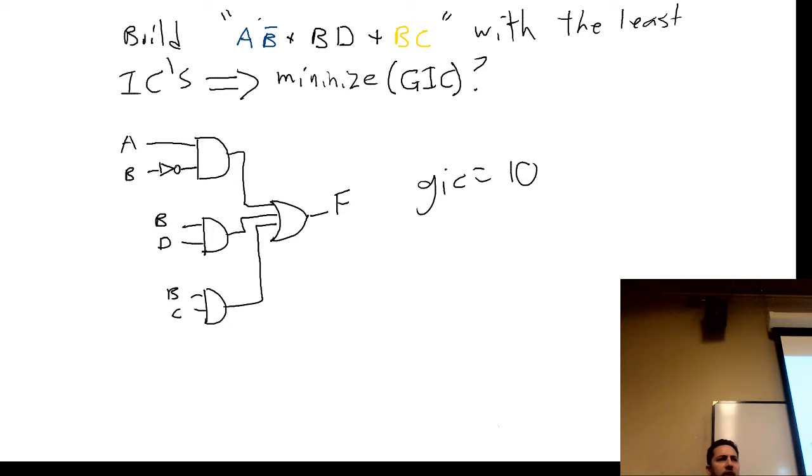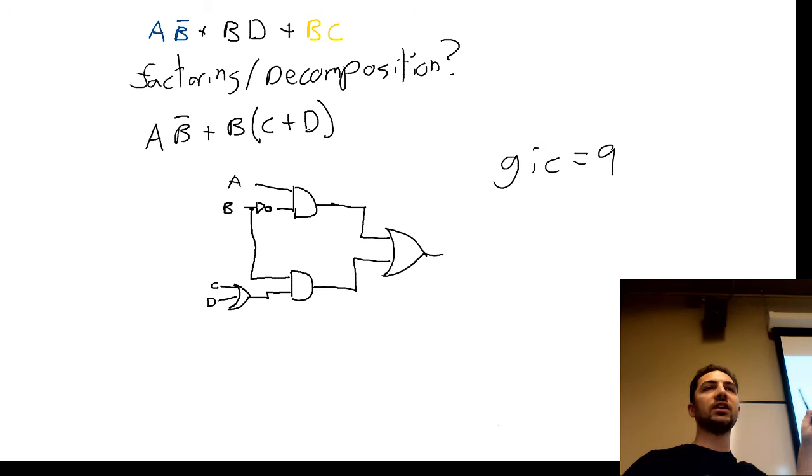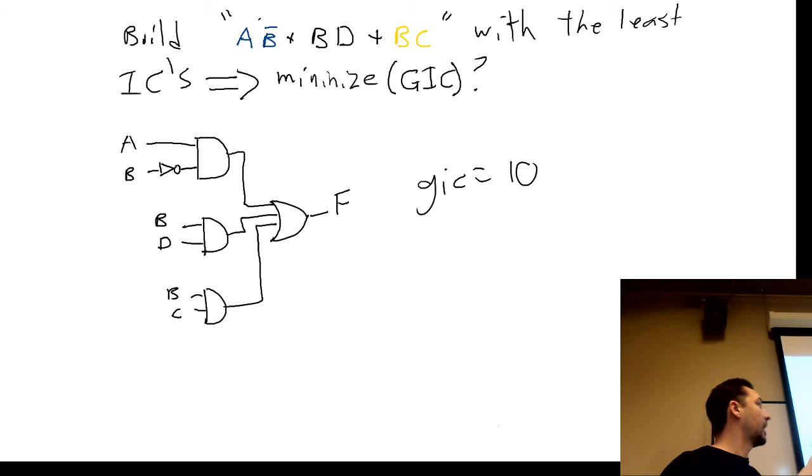You guys, in theory, have already turned in pre-labs for this. I haven't had time to grade them yet, but you should have read the lab. So what are the restrictions on what chips you can use? NANDs only. NANDs only. So does this have any NANDs in it? Does that one have any NANDs in it? No. So these are what we call logical schematics. They're the logic, ANDs and ORs and NOTs. We need to go and build technology schematics.